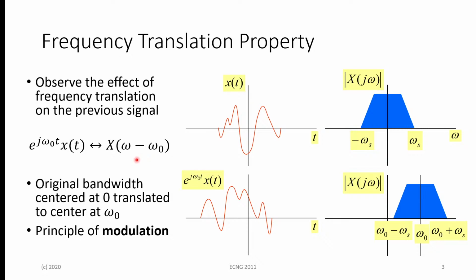So in doing so, after the signal is amplified and so forth, it actually is modulated, which basically is a simple form of frequency translation to move the signal contents from the kilohertz range into the megahertz range, which is required for the data transmission for GSM, which is going to be somewhere around 800 to 900 megahertz accordingly.